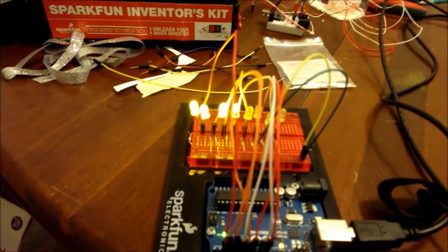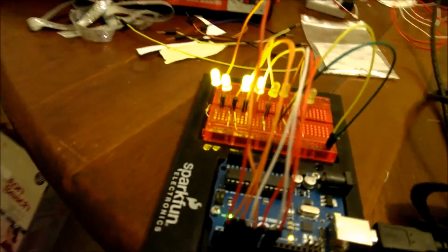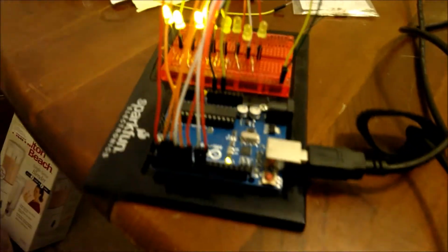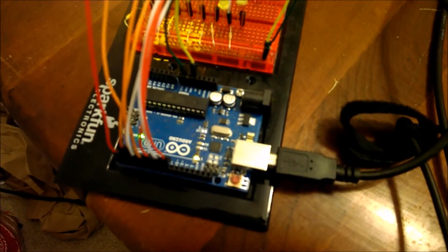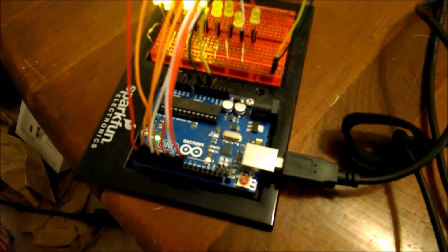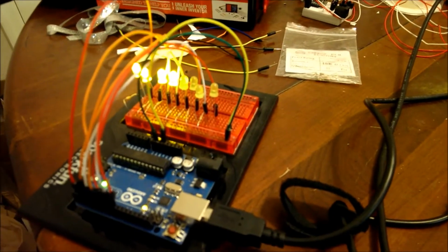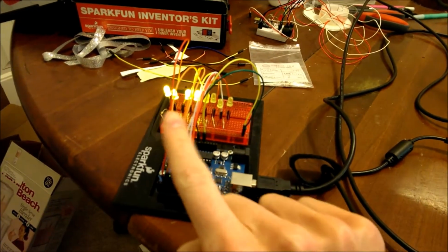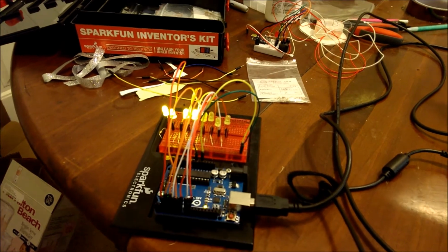So lately I've been working on teaching myself some basic circuits with my friendly little Arduino here. So you can see I've got my 8 LEDs set up. Basically each one has its own little resistor. The positive side of the LED goes to a digital pin on the Arduino, and then the negative side just goes to ground. So pretty simple setup. The example code just had it sweep, or something like that.